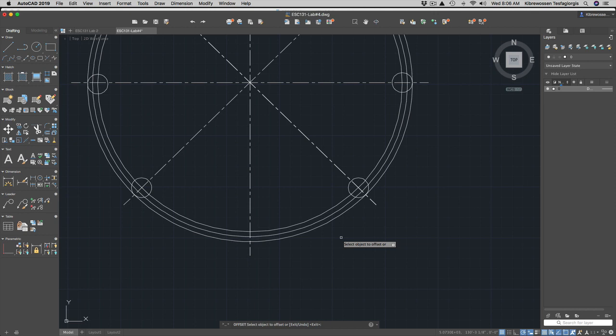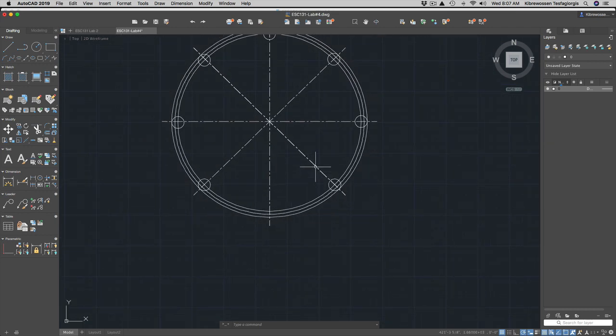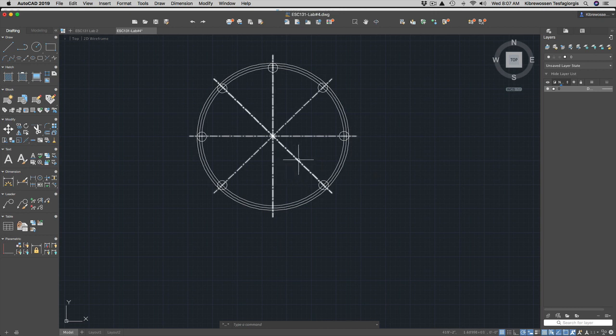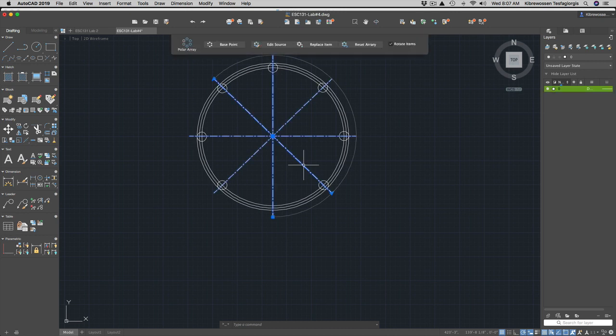Then you will see what I'm going to do with this. I would like to trim, but AutoCAD is telling me to use something 2 feet to this side and 2 feet off this side, and then trim that line. So the way I proceed is like this. I'm going to offset this line by 2.